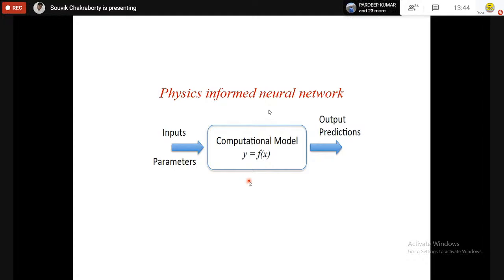So what we are trying to do now is, essentially whatever problem you are solving as a structural engineer is essentially a differential equation. So you already know the equilibrium equation, del sigma xx del x plus del sigma xy del y plus del sigma xz del z plus body force bx is equal to 0.